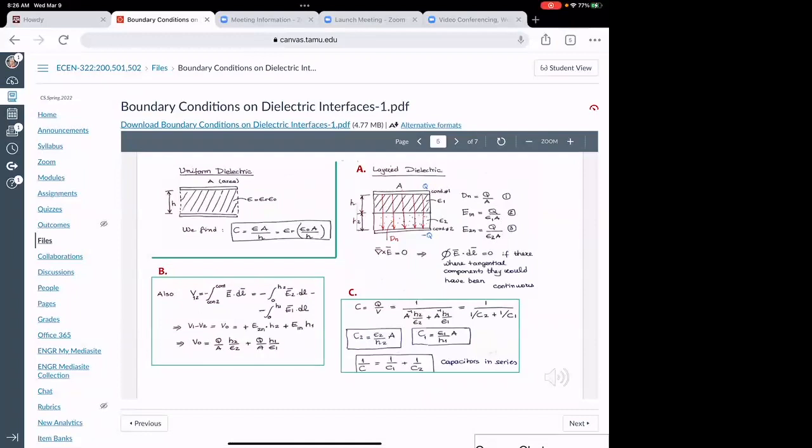If I want to increase the capacitance substantially, then I have to find a very dense dielectric, and what did I say? How high are the reasonable dielectric constants in whatever we use in electronics? Do you remember the number I said? Was it 10, 100, 1,000, or 10,000? Was it what was the maximum epsilon sub r that I mentioned in class for materials that you're going to see in real life in electronics? Close to 15, say, maximum, all right? 12.7 for gallium arsenide, and maybe a little higher for some other, exotic combinations. Close to 10, all right? So the maximum you can do in this capacitor, in terms of increasing the capacitance, is on the order of 10, all right? But